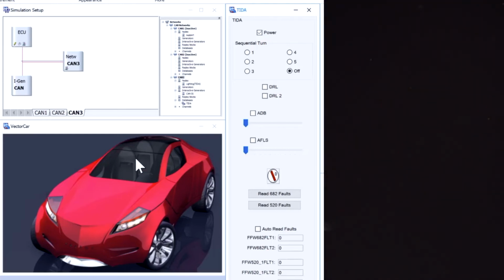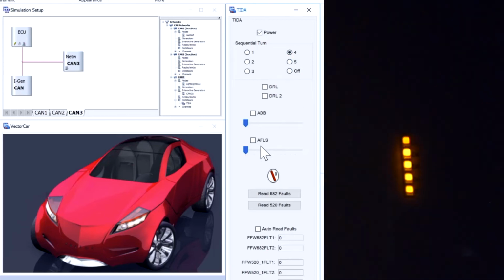And here's a sequential turn signal. The LED matrix creates a precise, smooth animation, and the buck continues to regulate unaffected by the dynamic load. The boost in front of the buck creates a stable rail that is always ready to provide a high enough voltage regardless of the LED string length due to the matrix.